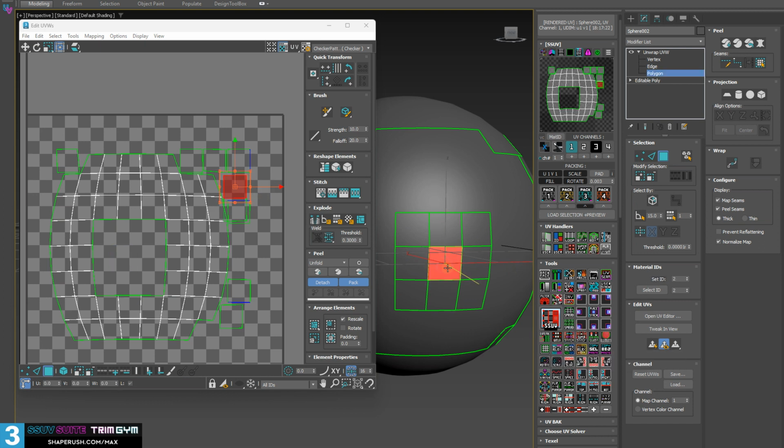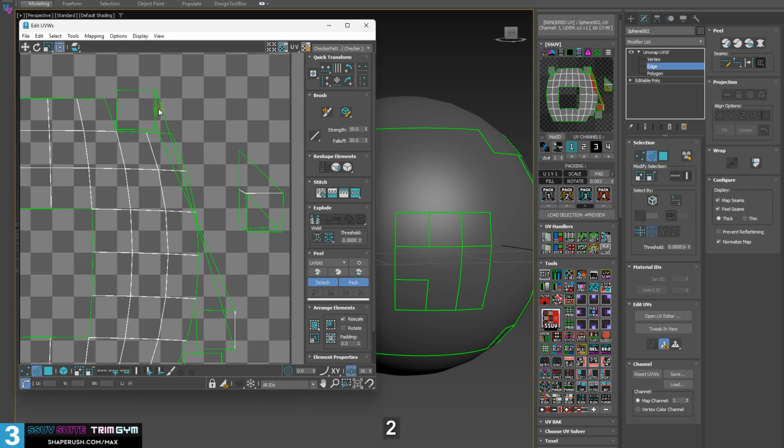Now let's do that again, and I'm going to right click. It's going to stitch from it to the other piece. I hope that works in concept because I can't remember the specific term that's used in Max. But you can see here that, maybe that was too close. Yeah, there we go. We can use these two. So I'll take this one and I'll right click stitch. You can see it sends that edge all the way over to be taken care of for the stitching.